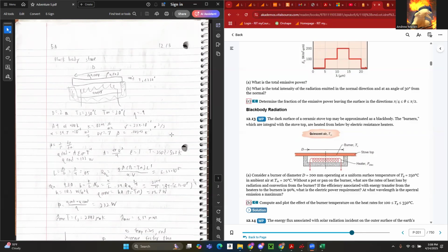You can find all the values necessary to compute beta in table A4 if you know the temperatures. Then you multiply all that by the change in temperature times the characteristic length cubed, all over the dynamic viscosity and thermal diffusivity. Once again, these values can be obtained from table A4, which gives a Rayleigh number of 6.35 times 10 to the 5 power.